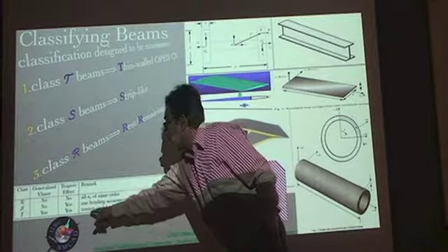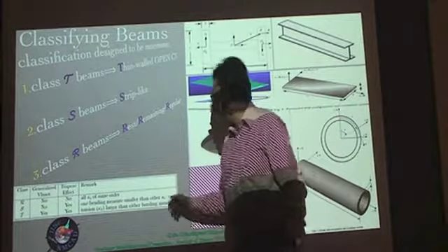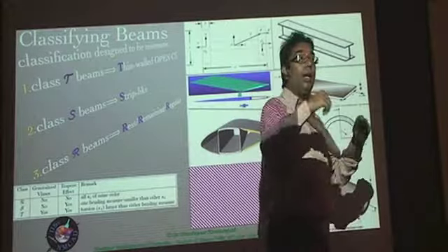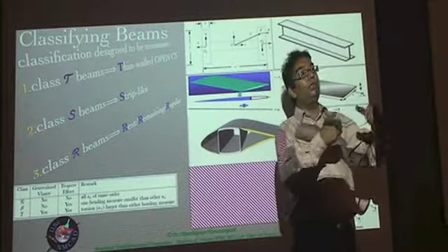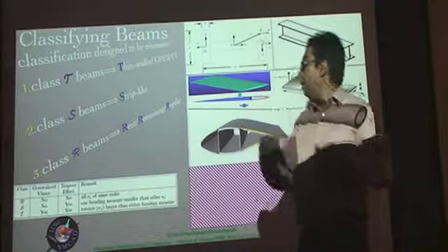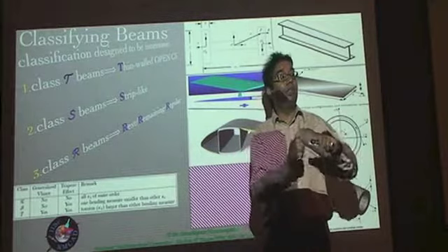The next situation is where you have thin-walled open cross-section. Torsion is larger than either of the bending measures. For example, an I-section beam, of course, you would have a difference in bending stiffness in the two directions, but not an order of magnitude difference in the bending stiffness. And that's why you see that in terms of bending, there's not too much of a difference.